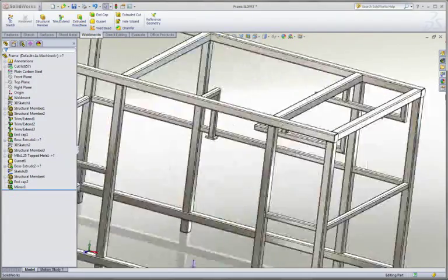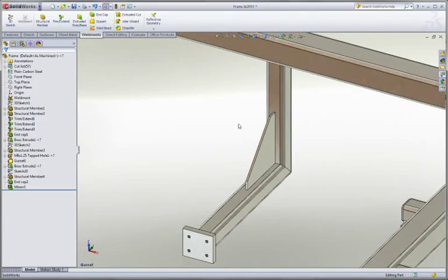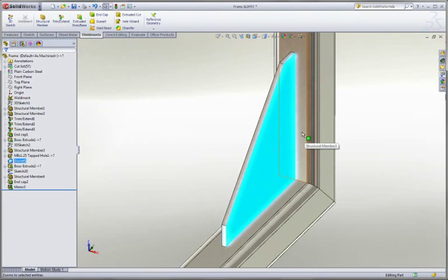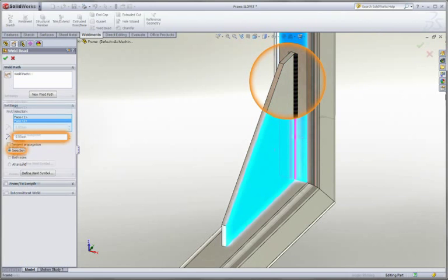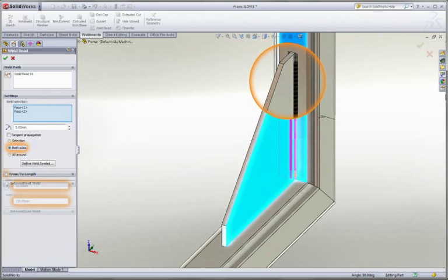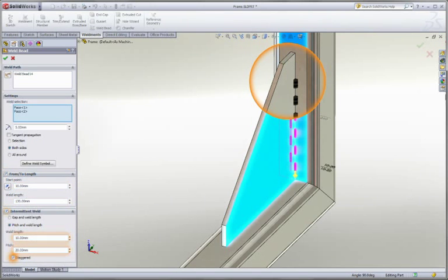We've completed all of the major design elements to our frame, but there's one significant piece missing: the welds themselves. Like every other tool in SOLIDWORKS, we'll see that we can quickly create any type of weld we could imagine, from single straight welds to a weld on both sides. We can control the offset from the ends and, of course, intermittent and staggered conditions.